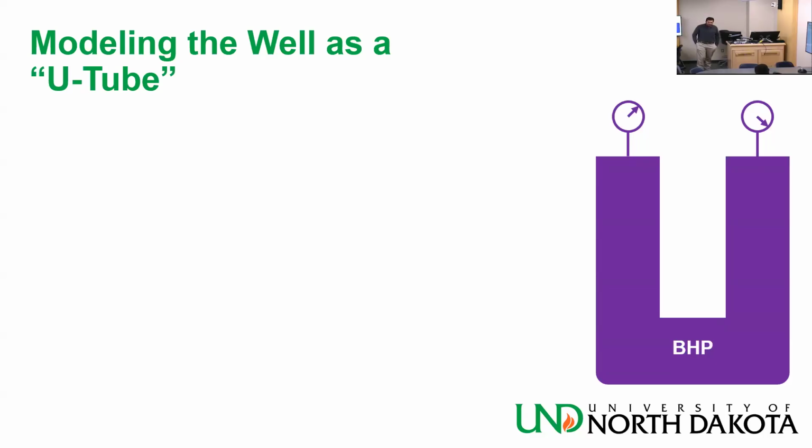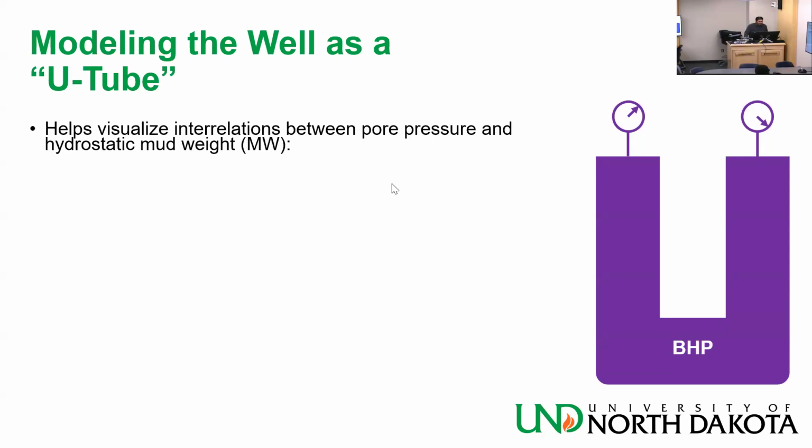It's still applicable, but you need to make some adjustments. So it doesn't matter how difficult the problem is. It will be a more complicated model, but you can still use the U-tube model to derive equations that you can use to solve your problem. It helps visualize interactions between pore pressure and hydrostatic mud weight.